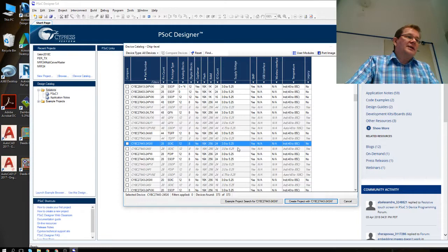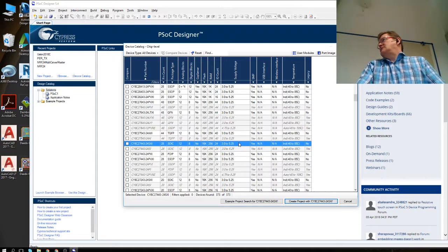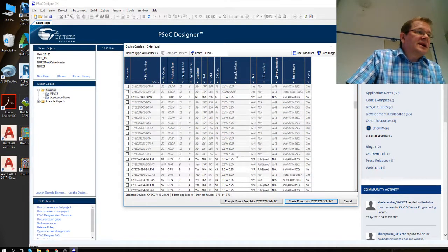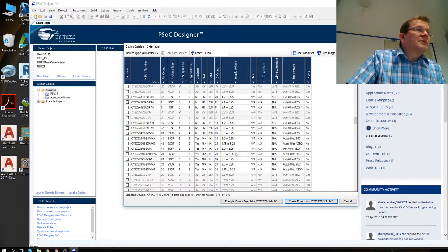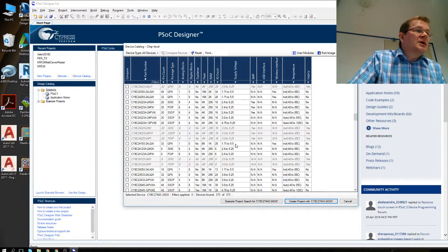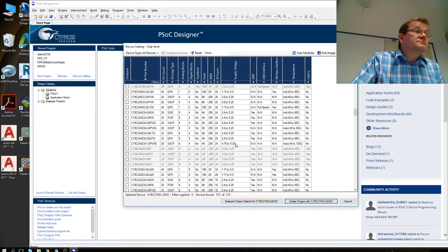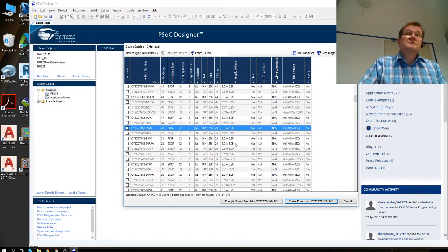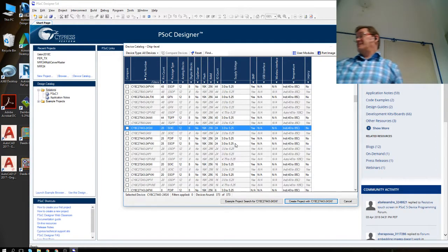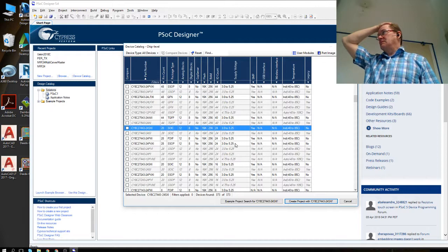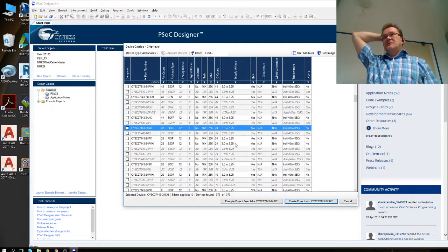Power supply range is from 3.0 to 5.25. Well, that's nice. Although this can range from 1.75 to 5.5, it's actually the highest ones. But anyways, with this SMP, you can run this processor from a single cell, 1.2 volts actually, or less than that. 0.8 volts is the lowest battery voltage where the charge pump still works.